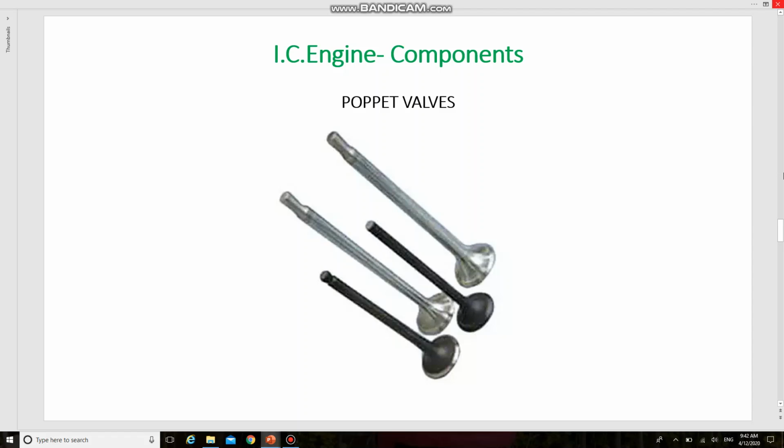In an IC engine, it must be petrol or diesel or any type of liquid fuel. By opening or closing or partially obstructing various passageways, the intake and exhaust valves open at the proper time to let in air and fuel and to let out exhaust. Note that both valves are closed during compression and combustion, so that the combustion chamber is sealed. The material may be phosphor bronze and monel metal.